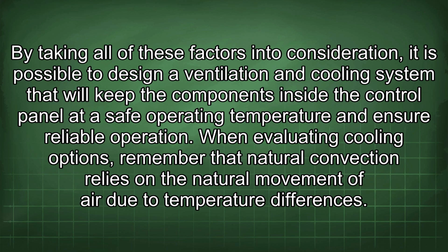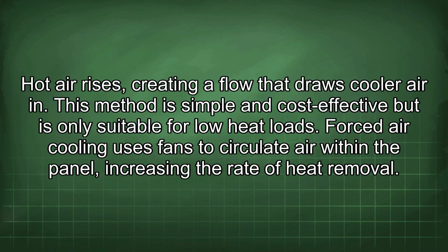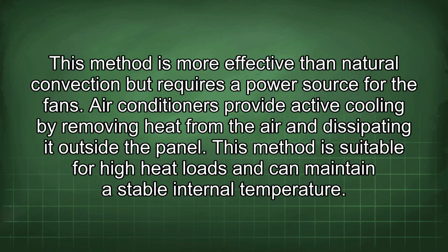When evaluating cooling options, remember that natural convection relies on the natural movement of air due to temperature differences. Hot air rises, creating a flow that draws cooler air in. This method is simple and cost-effective, but is only suitable for low heat loads. Forced air cooling uses fans to circulate air within the panel, increasing the rate of heat removal. This method is more effective than natural convection, but requires a power source for the fans.